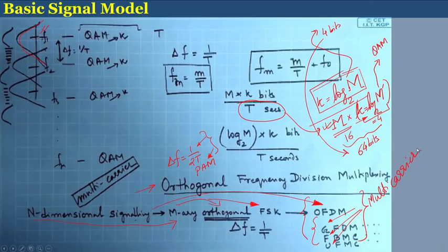When we say multi-carrier, what we mean is that you are sending all these carriers simultaneously while maintaining the orthogonality criteria, that although overlapping, they have zero correlation amongst them. This is the basis for multi-carrier signaling, and in some form of 3G, multi-carrier CDMA was also proposed, and how to place these multiple carriers was also investigated in quite deep detail. There is a huge amount of literature available on multi-carrier signaling.